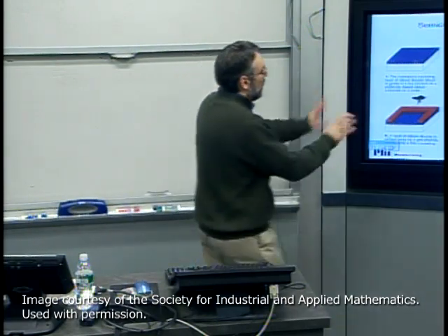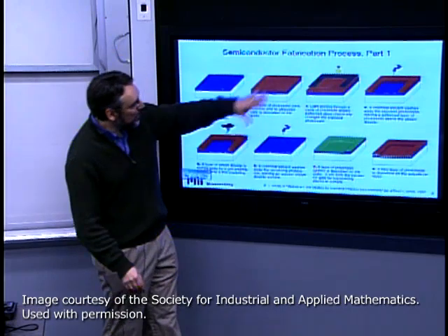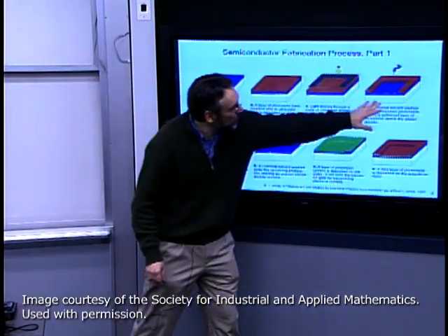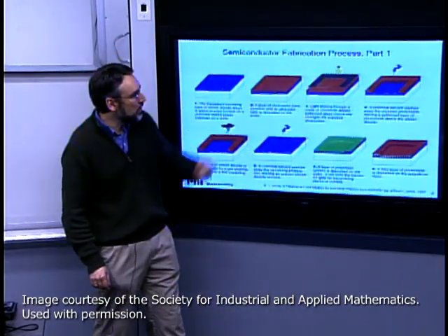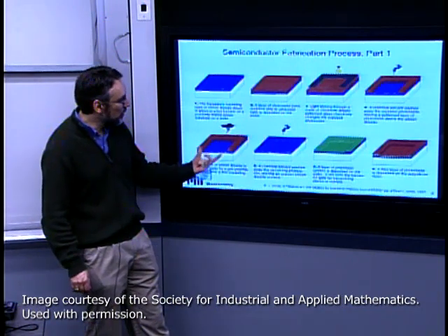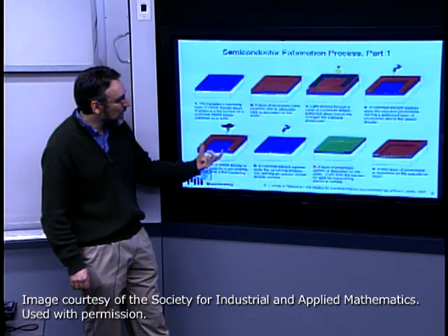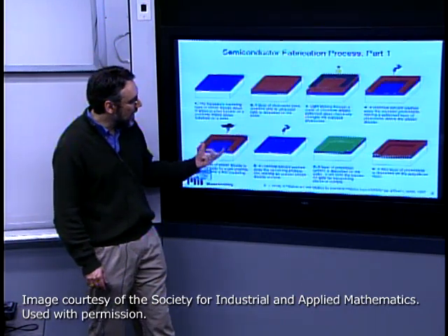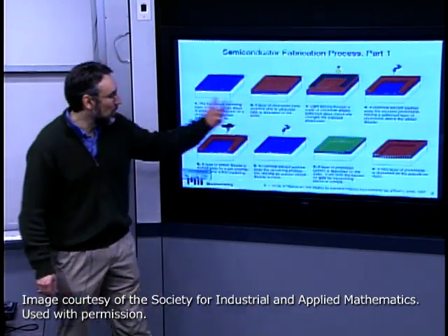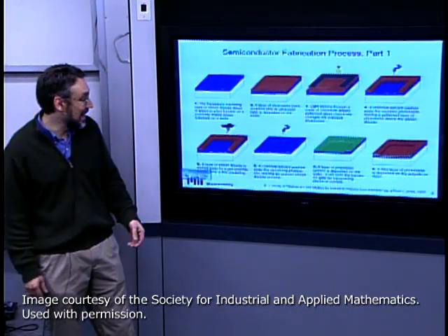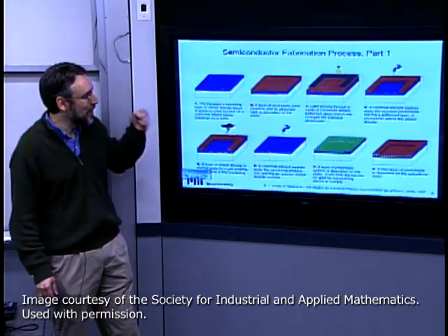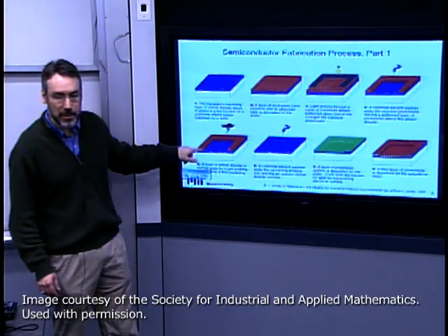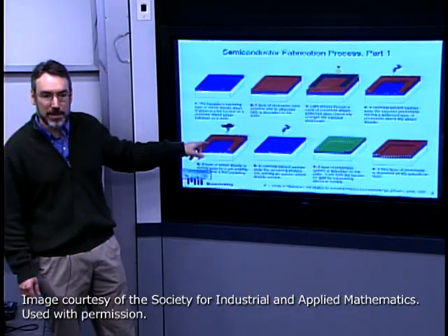So, still sort of taking this at face value, we had the photolithographic sequence that imprinted onto the photoresist. We used that then to controllably change the permanent structure, the silicon dioxide, and then we remove it using another chemical solvent, or in many cases another plasma etch, a plasma ash, that removes the temporary photoresist.